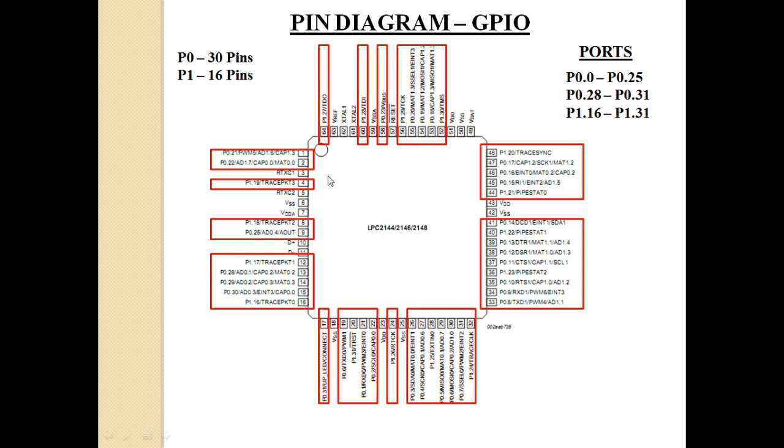And here it is having special packaging known as LQFP, low profile quad flat package. Low profile means the thickness of the IC will be very less. So it is a 64 pin quad flat package. This will be pin number 1. This will be pin number 64. We will generally be calling it a GPIO port. Right, so you will be calling the GPIO peripheral a GPIO port. So what do you mean by port? Port in this scenario means it is a collection of external pins.